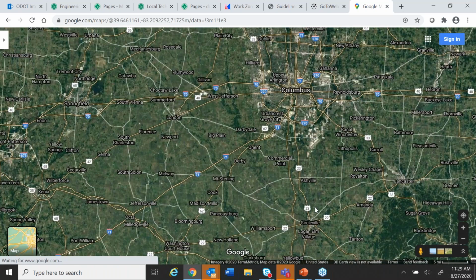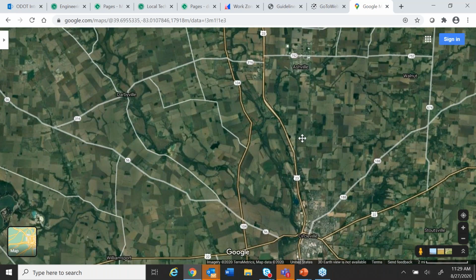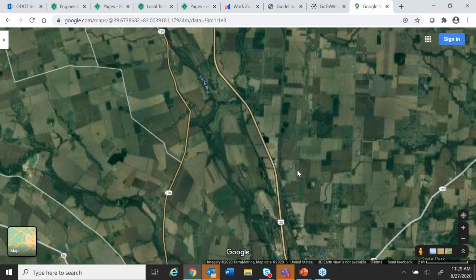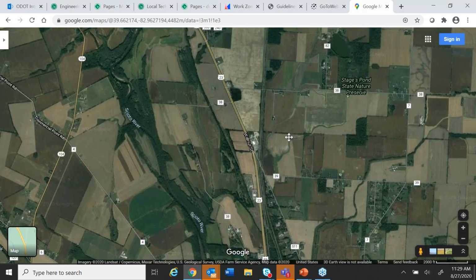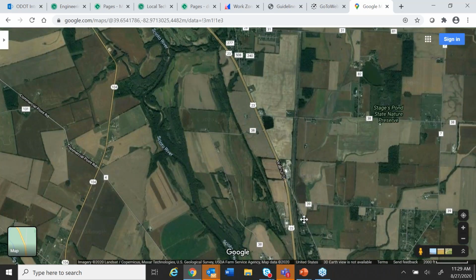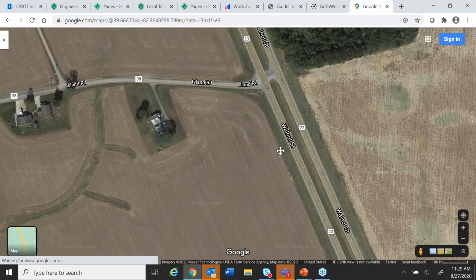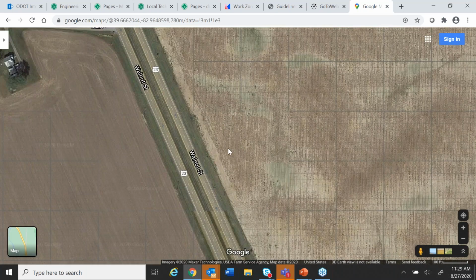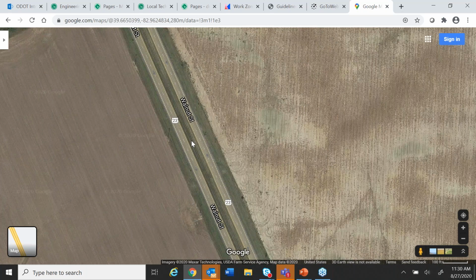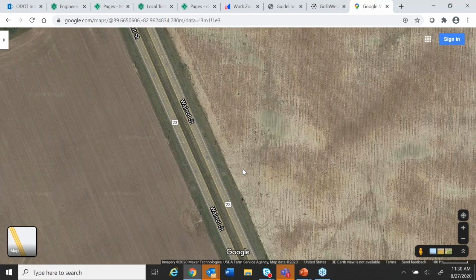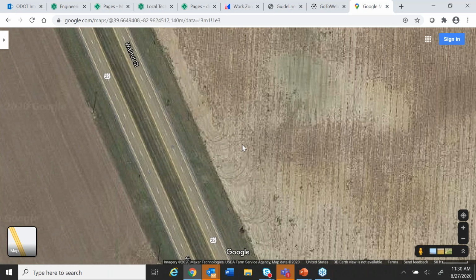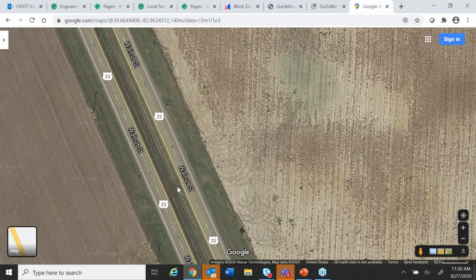Near Circleville, of course, we've got different roads. But what if I was on Route 23 in this area? It's a 4-lane divided roadway. For some reason, it's called out as Walnut Street here, but that's Route 23. So if I was going to close the northbound right lane, which typical application would I use as the basis of my design out here?